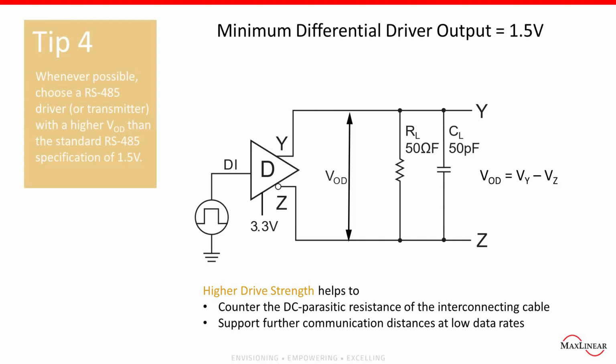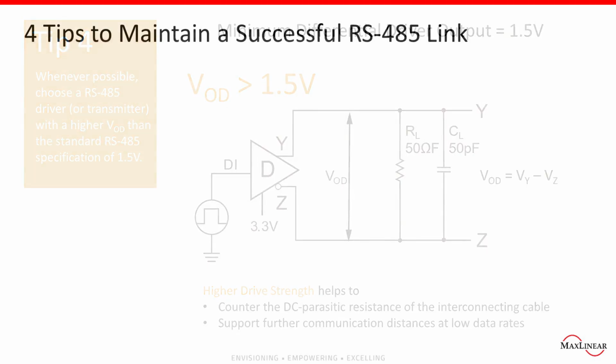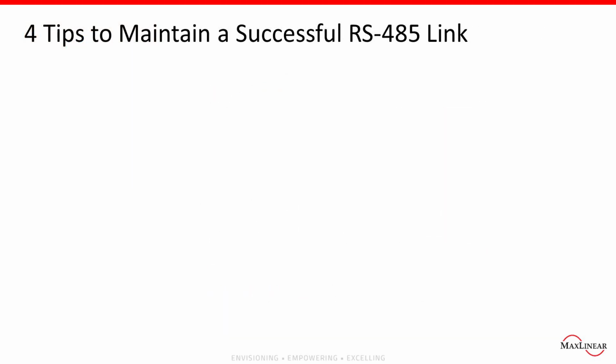Tip 4. Whenever possible, choose an RS-485 driver or transmitter with a higher VOD than the standard RS-485 specification of 1.5 volts.